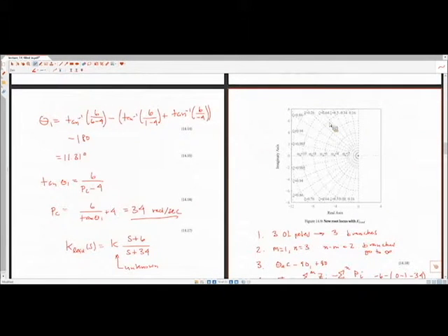Okay, so then plotting these items on the root locus plot, we have a pole at the origin, a pole at negative 1, a zero at negative 6, and then I have a pole that's way off my chart. Negative 34 doesn't show up on my page here. It's way over to the left. But it's still in the system, right? It's just way off my chart.